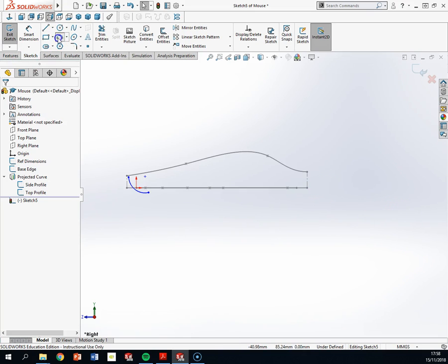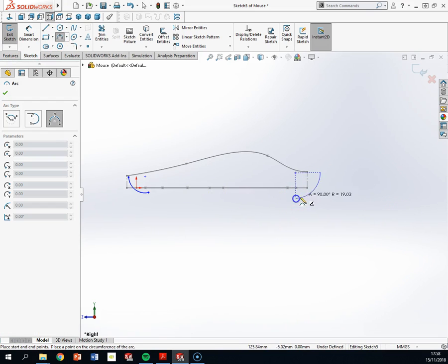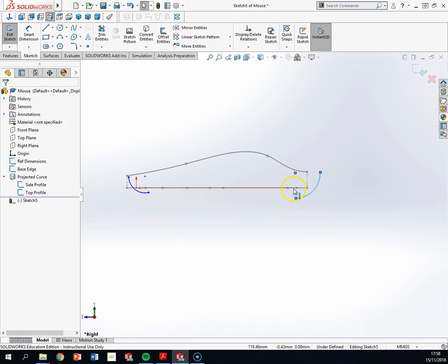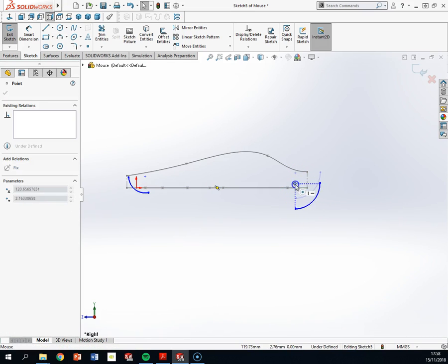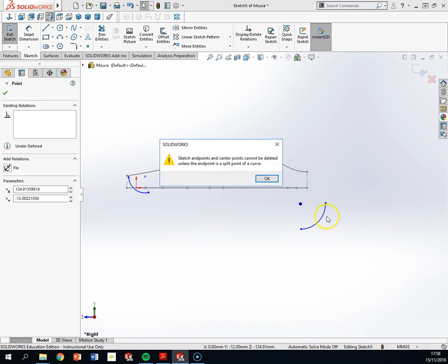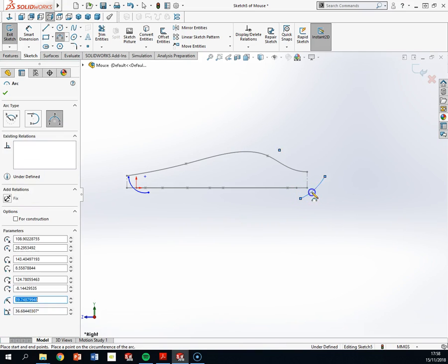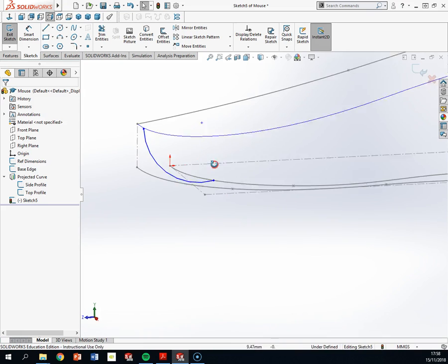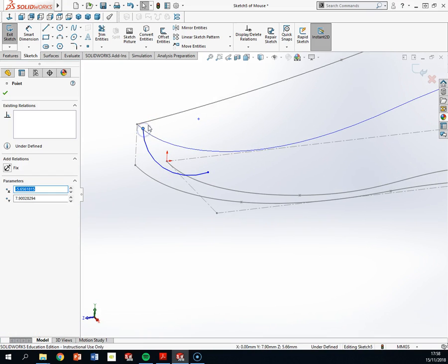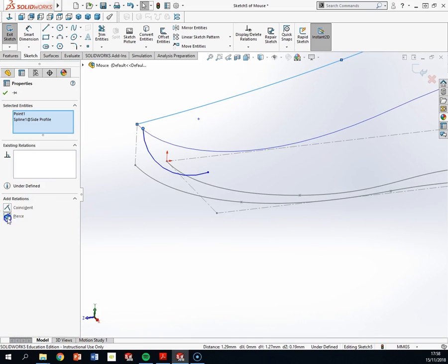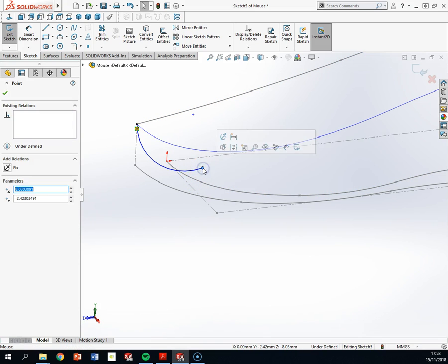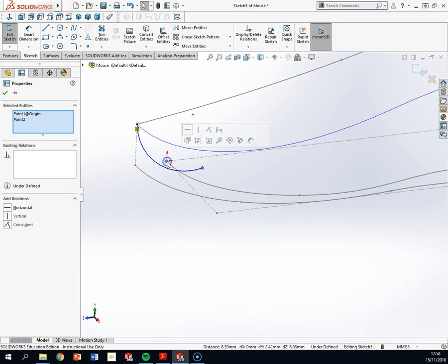I'll do the same over the far end, 1, 2, set the curvature, and that's locked into a quarter circle shape there. So I'm just going to delete that for a second, go again, 1, 2, and kind of set the curvature there like that. Now I'm going to pierce this point onto this curve here, it needs to be attached, and I can do the same with that one there, and I think I can just make that coincident.